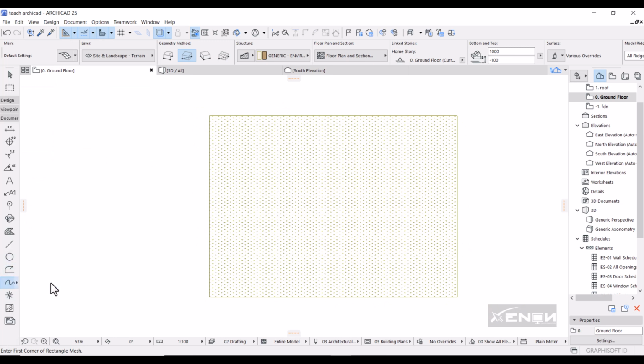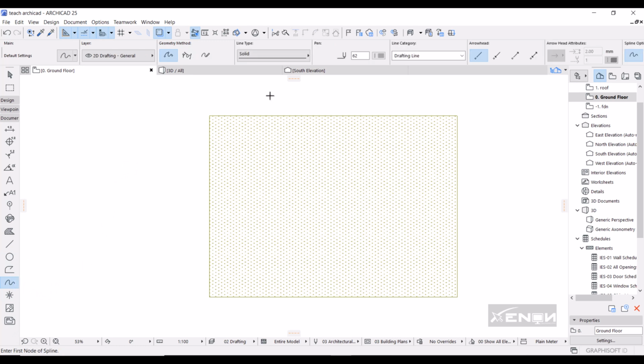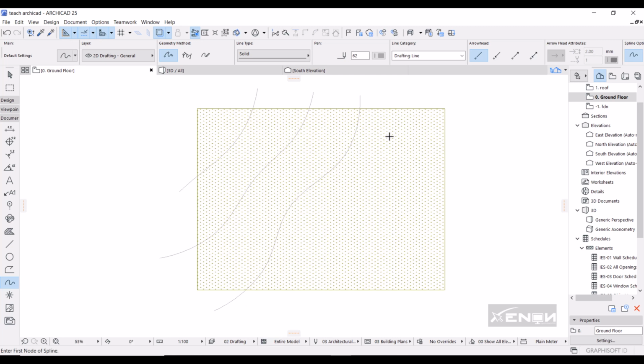and then you're going to head over to your document. You're going to grab your spline tool. Now the use of this spline tool is to draw contours into this thing right here. Perfect. So I'm going to draw contours. In most cases you have a map and you simply trace out these contours, but for purposes of our tutorial I will simply draw. Now make sure that the contours you draw actually go beyond the mesh. I'm not giving you the reason for that, but just make sure once you become experienced with these things, you'll find out the reason.